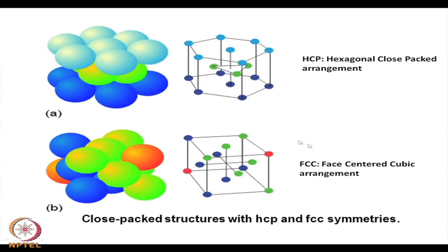For example, in the hexagonal structure, all the horizontal planes are slip planes, and the horizontal planes are close packed planes, whereas the vertical ones are not close packed. The vertical ones are open, and therefore, if the atom has to go to its next equilibrium site, for example this one, it has to move vertically this much. Whereas in the horizontal plane, if the atom has to go to the next equilibrium site, which is this one, the distance of separation is much less.